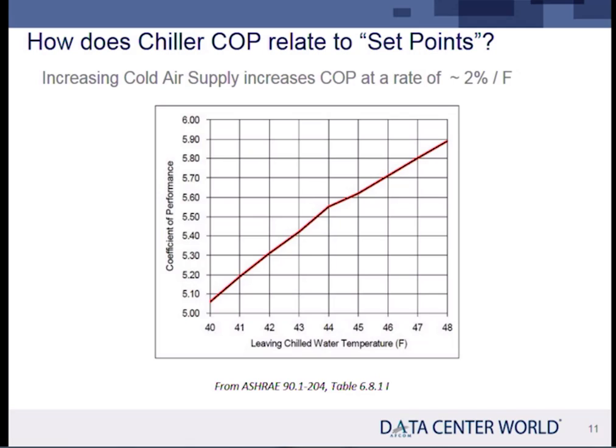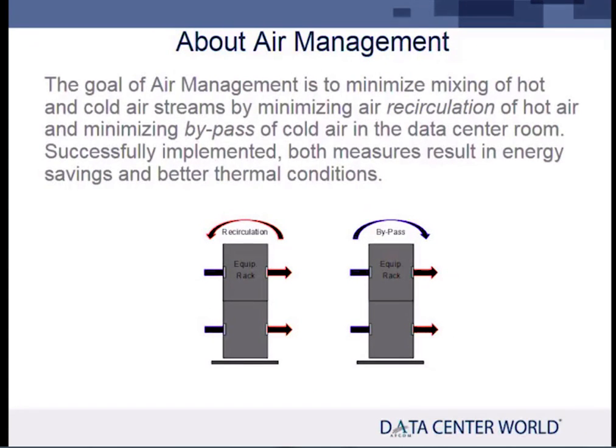So the first question you think about when you say raise supply air temp, am I going to have hot spots? Now the only way you'll know really that you're going to have hot spots is to model it, to try it, have a mechanism for trying it out. And I am an advocate of modeling. I'm in the modeling business because it's airflow. And managing that airflow and knowing where that air is going is very important to a couple different things. We talked about the heat exchanger, but also hot spots, getting the air to where it needs to go.